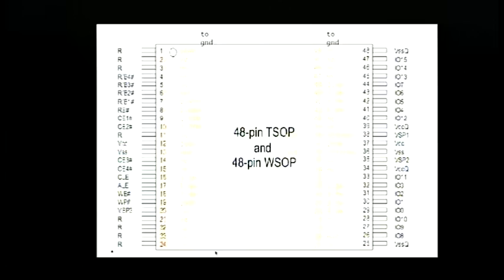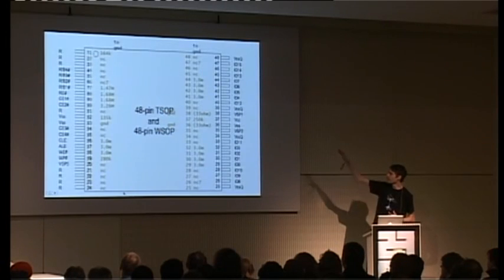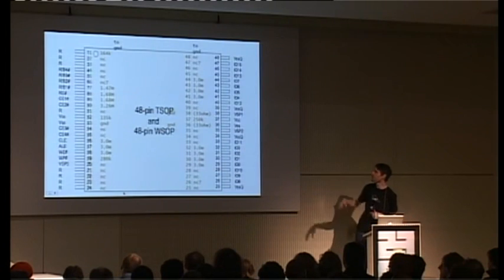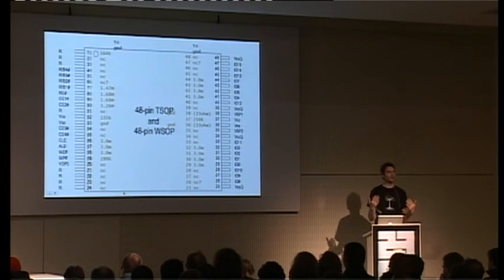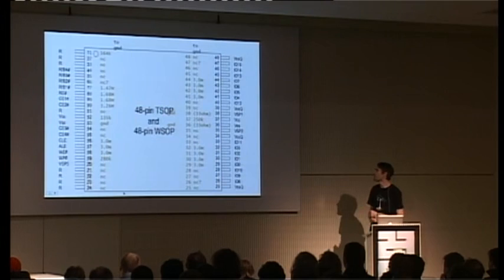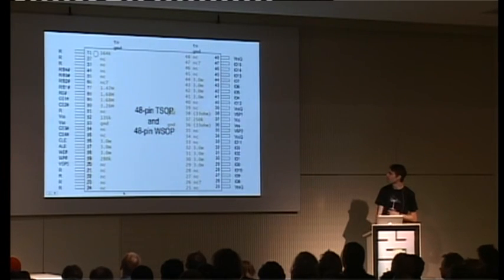And I compare this to the ONFI standard, which is a sort of standard for compact flash interfaces. It gives you all these different footprints and what the common pin layouts are for it. So I started to compare the pattern that I see with patterns that should be on the footprint. So for instance, I would think that all of the I/O pins would have the same resistance. And here in this comparison, you can see that it doesn't quite match.